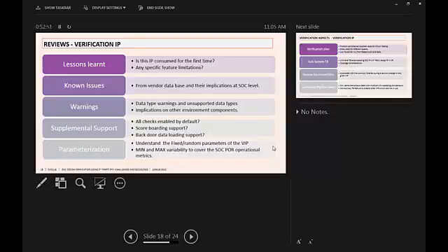So here I see the issue is with UVM, error to warning, because this came from the common libraries you could have used across different VIPs. So for some SATA or some PCIe, they change this to a warning, but for PCIe I may require this one as an error because there is some data integrity error. But this has converted the error to a warning, and my test case failed because of some other reason. Then only I was checking why the scoreboard was not throwing an error because of this.